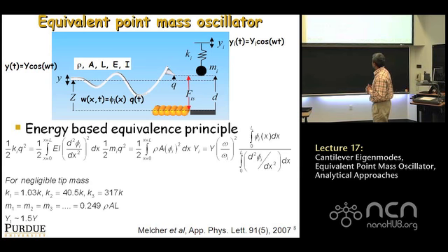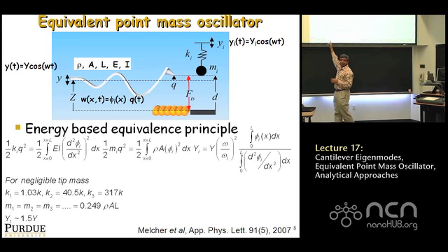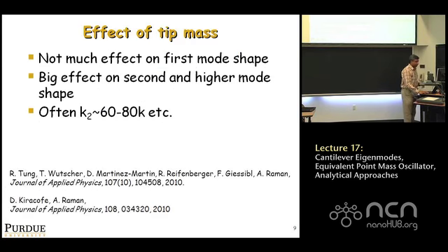All right. The interesting thing, though, is in this analysis, the mass of this oscillator, regardless of the mode you're in, is the same. So as you go to higher modes, the equivalent mass does not change. It's only the stiffness that changes. Okay. So the details are shown in this paper. Now, remember, in all this discussion, I neglected tip mass.